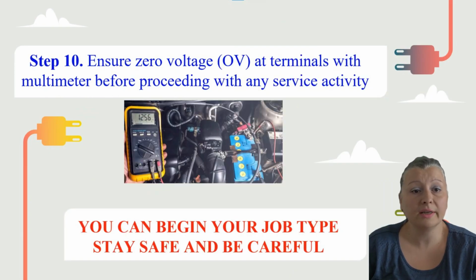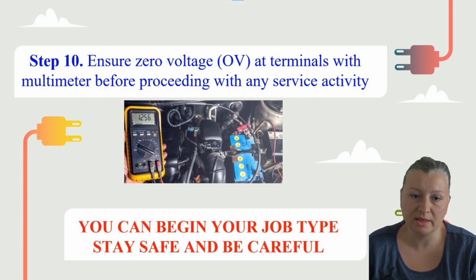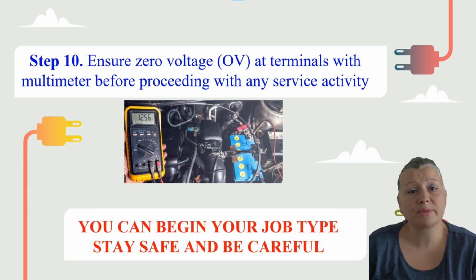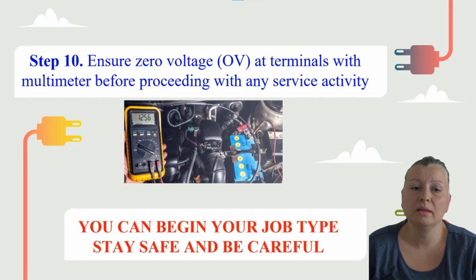And the final step, Step 10. Ensure zero voltage at terminals with multimeter before proceeding with any service activity. After all the steps were taken, you can now begin your job. Stay safe and be careful.